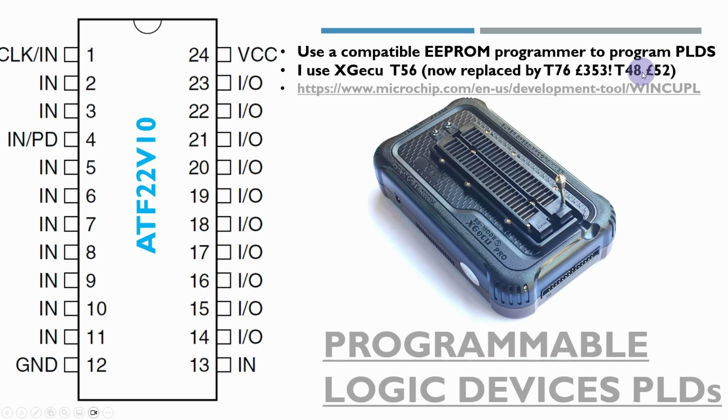Just be aware, however, that some of the chips I use in the PLD series can only be programmed by the higher-end programmer. The one I'm showing you here will work with this T48, but just be aware and watch the whole series before you go out and buy a programmer. Make sure that you're happy with the trade-off that the cheaper programmers will do a lot of things, and to be honest, it's only the more exotic chips that you will need the high-end programmer for.